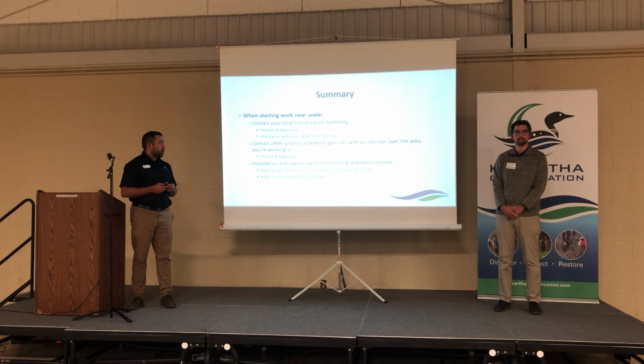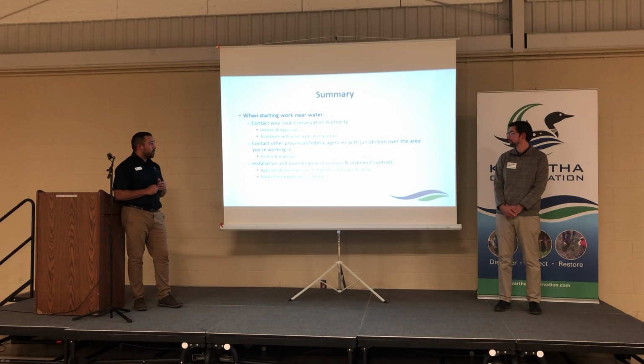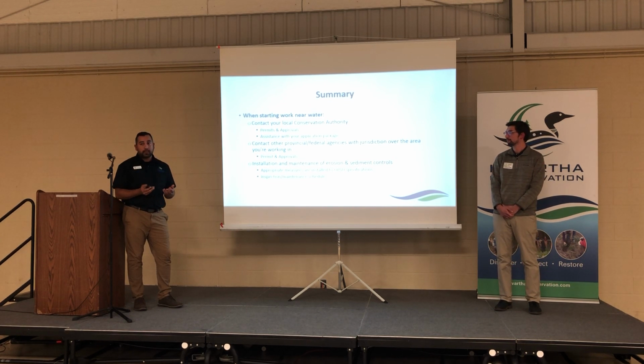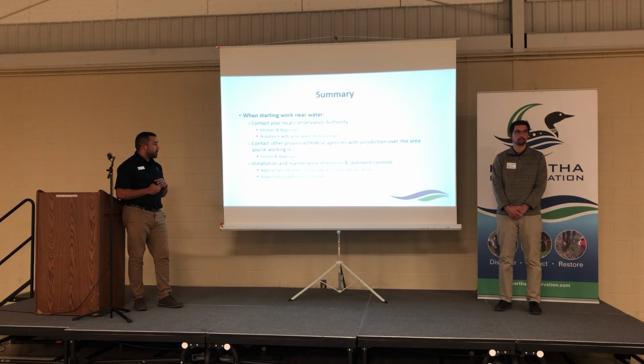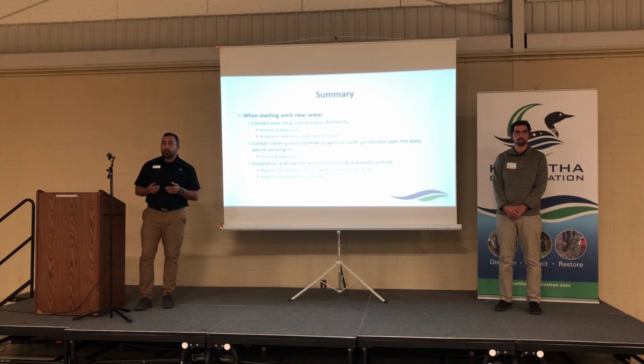We've touched on quite a few of those, just to check for permits and approval requirements. And it's also good to understand the installation and maintenance of the erosion and sediment controls that would be required through your permit, or even additional controls that might be decided at a later point once works are underway on the site and staff have a better understanding of where sediment and silt are traveling and where the concerns are going to be. And it's also really important to think about having an inspection or maintenance schedule once the work is started on site so that you can stay ahead of any of the sediment and erosion concerns that might come up.